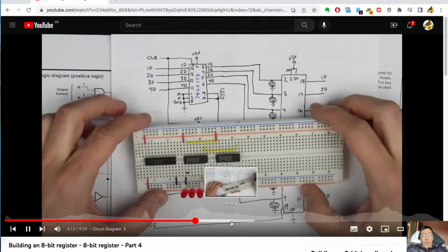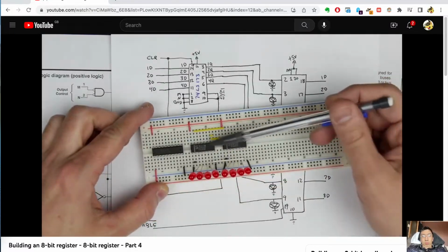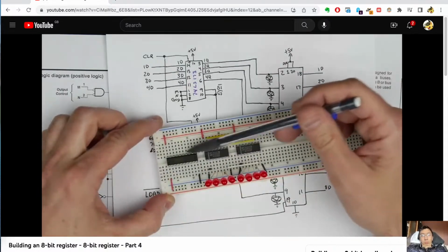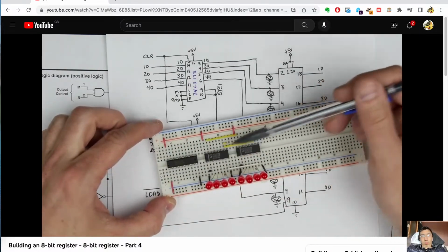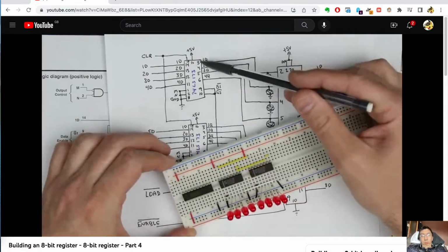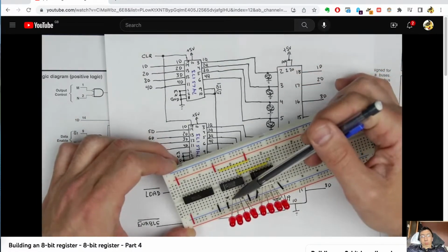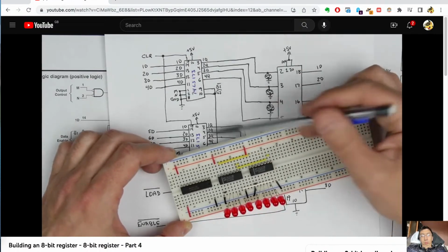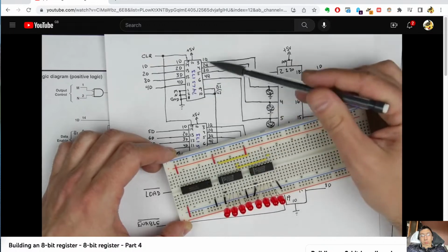So I've started to build this here. These are the 2 74LS173s. These are our register chips, and then of course our 74LS245 over here, which we're essentially using as the output buffer. And I've got some LEDs hooked up here, just kind of stuck in on the outputs. So you can see pins 3, 4, 5, and 6 are connected here. I've got the LEDs there. Same thing over here. Pins 1 and 2, as you can see here, are tied to ground, and that just enables our output all the time.